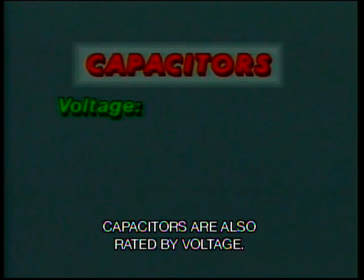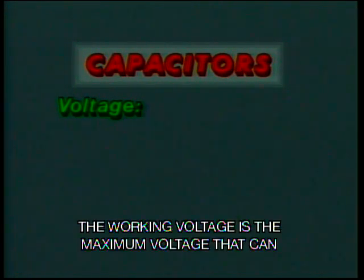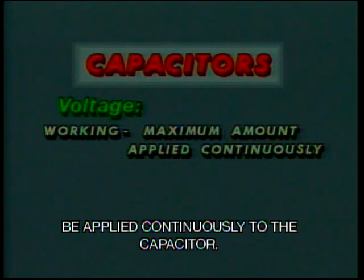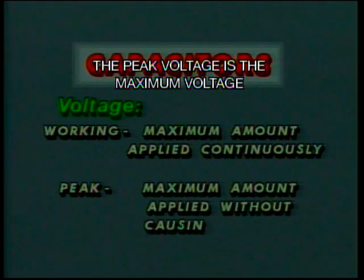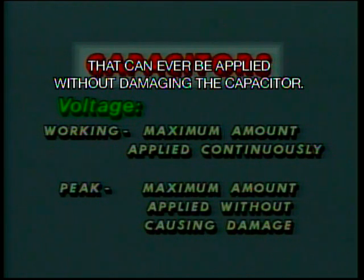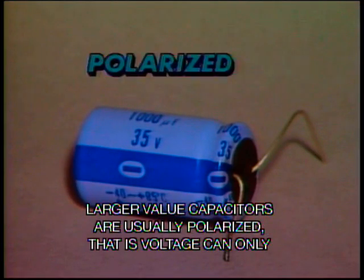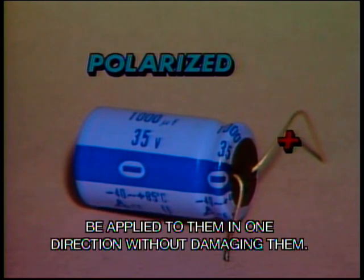Capacitors are also rated by voltage. The working voltage is the maximum voltage that can be applied continuously to the capacitor. The peak voltage is the maximum voltage that can ever be applied without damaging the capacitor. Larger value capacitors are usually polarized. That is, voltage can only be applied to them in one direction without damaging them.